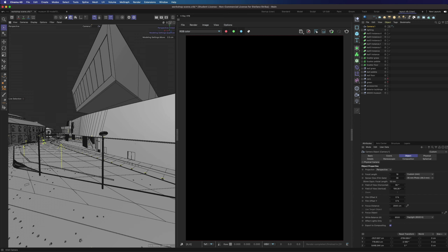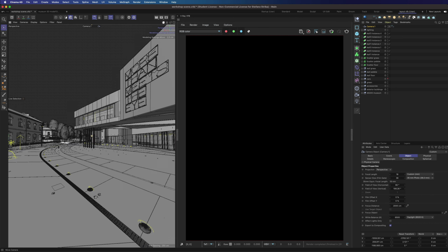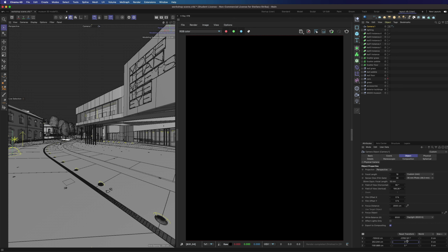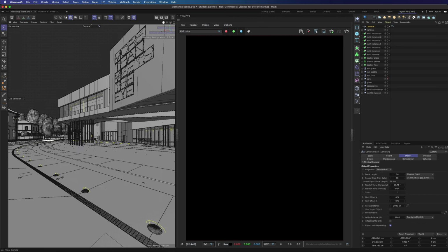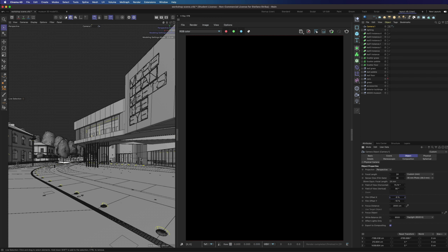It's important to position the camera in the right spot, always trying to find lines that will guide the observer. For architectural shots, usually it is best to not have a vertical deformation, so always put 0 on the y-axis. Here, for example, we can use these two diagonals, the metal grid on the floor and the top right corner of the building. If needed, we can also tune the position of the two diagonals using the X and Y film offset, so that the lines start from the corners of the image.